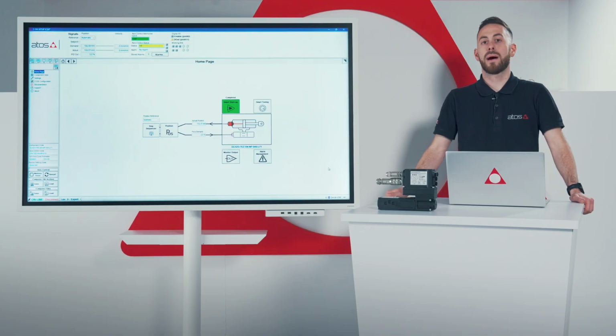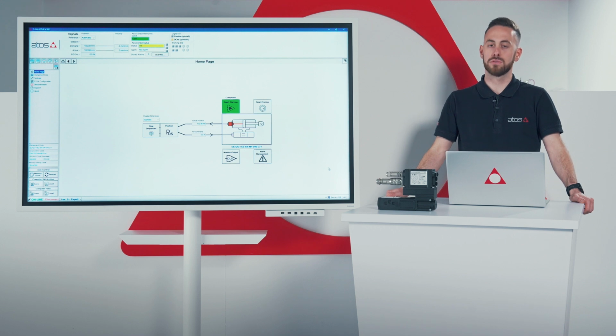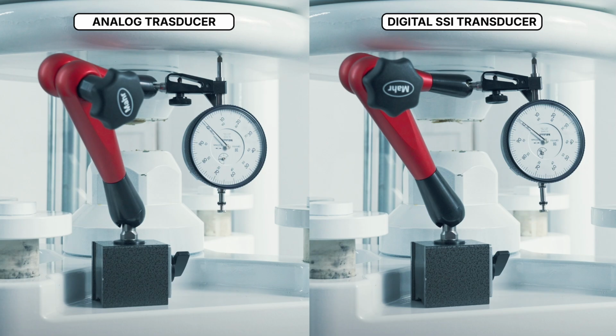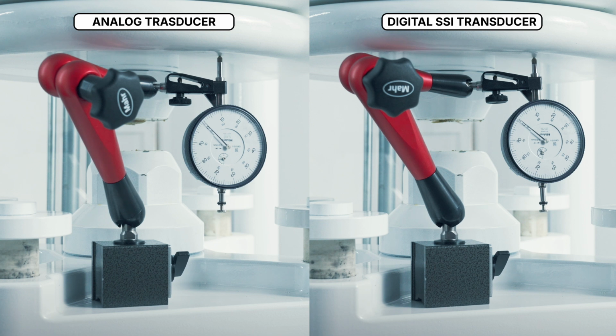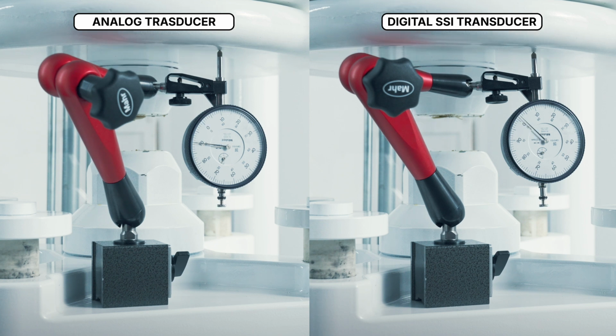In fact, by increasing the value of this gain, the risk is to introduce vibration during the movement of the axis. As a result, the positioning performance will be lower, with a slightly more unstable position entry and a slight overshoot, as you can observe from the instrument reading shown in the video.